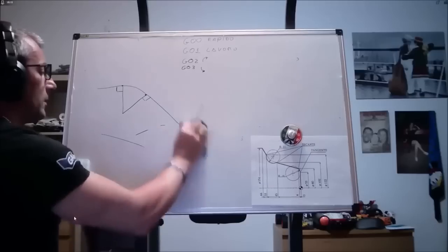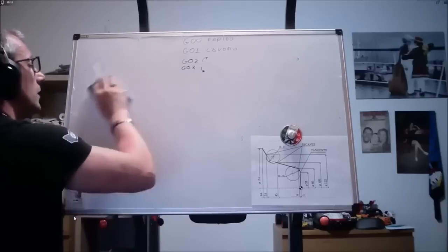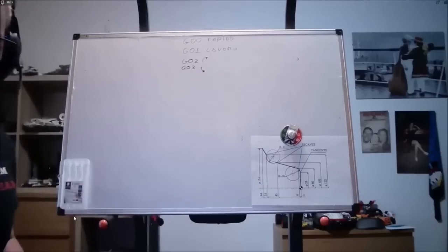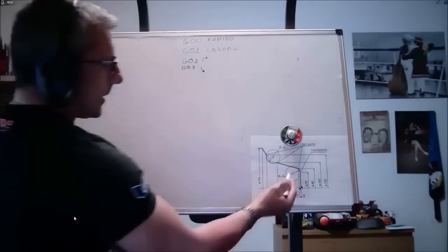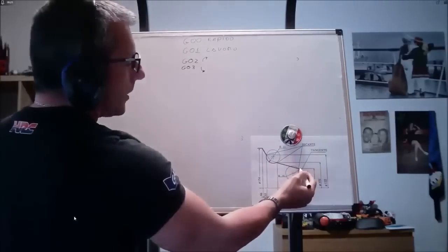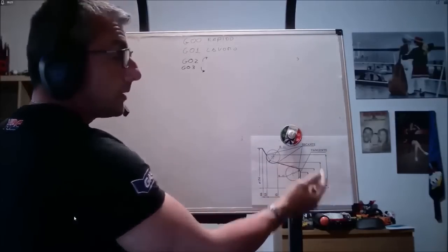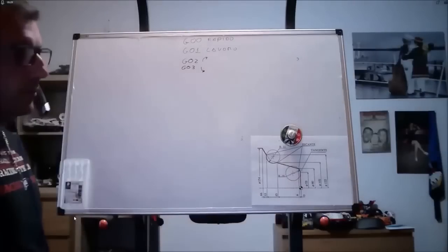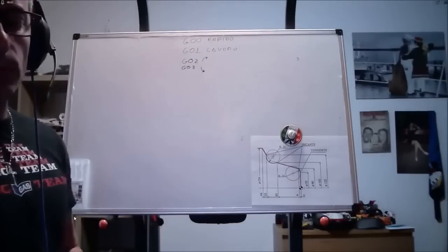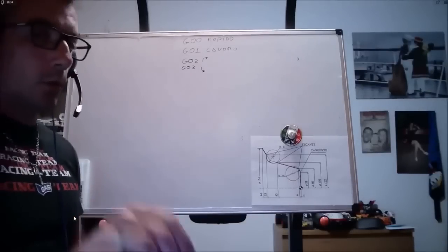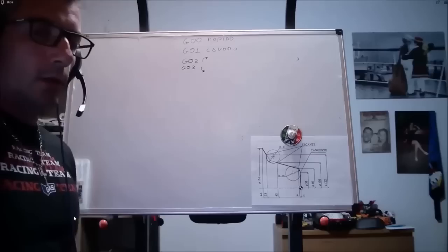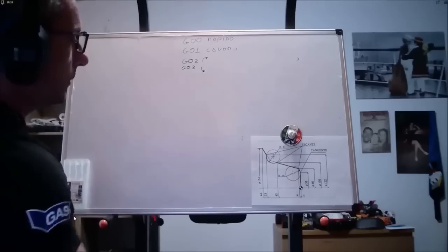Now, regardless of this, with G02 and G03 we have learned to create circles that can be both tangent and secant. With direct programming, radii can be created much more easily. We will see this in the next tutorial.